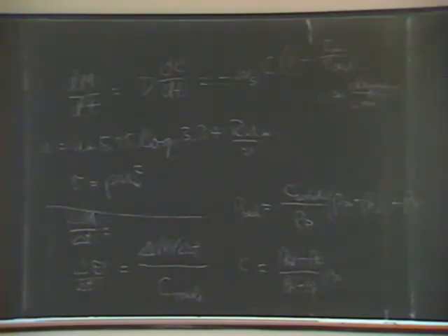It's the suspended solids that cause the sedimentation. Suspended solids combined with the hydraulic conditions in the harbor area cause the sedimentation. So either you have to keep it moving through or you have to keep it from getting there in the first place. Now, moving it through means minimizing the amount of sedimentation that occurs and providing currents that sweep out what does deposit.